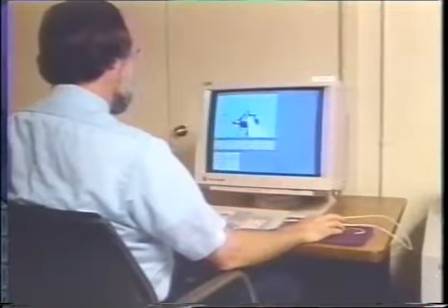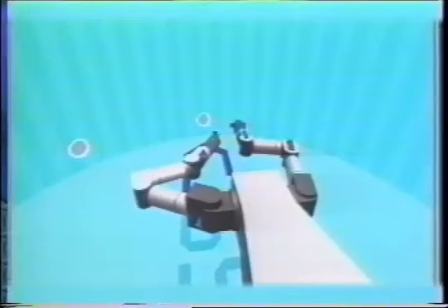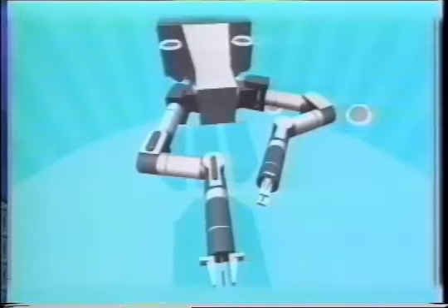The fundamental problem, which is addressed by our Ranger augmentation, is that of avoiding collisions between a dexterous robotic arm and objects in the environment, such as other arms, the base, and the task board. Perturbations to arm trajectories for collision avoidance must be made gradually in order to avoid sudden jerks, which can damage the arm or lead to undesirable oscillations.